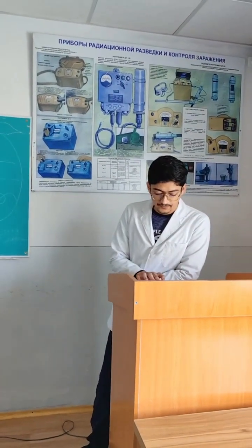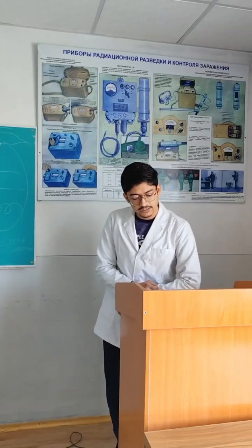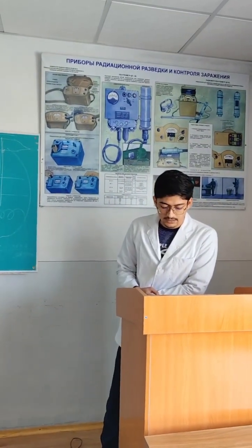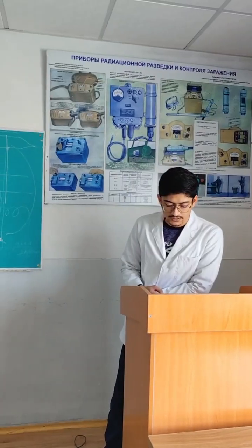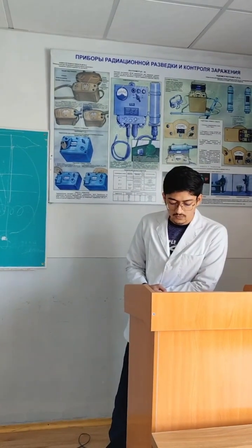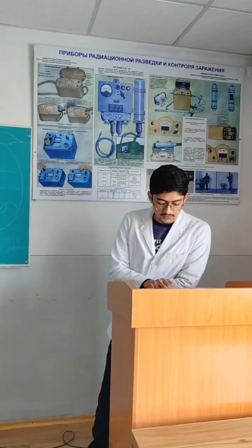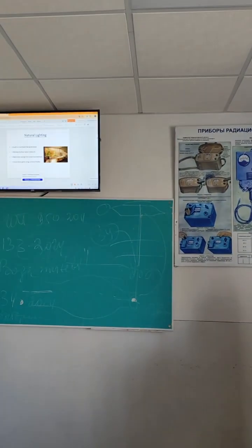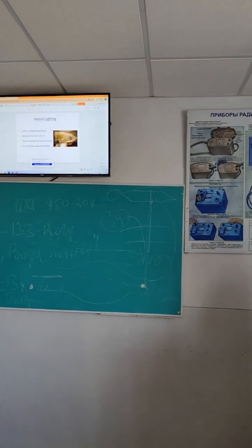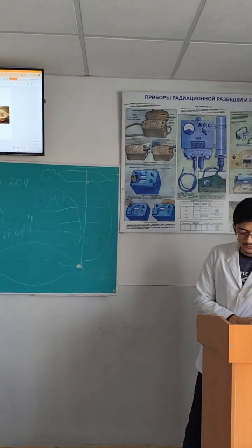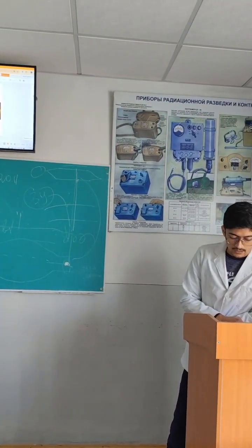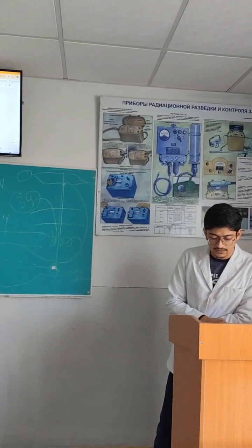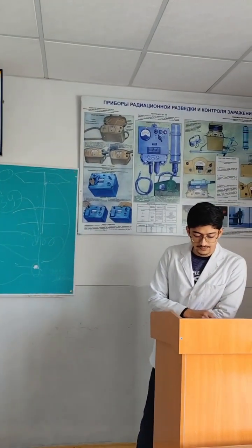Principle of placement. Building position for sunlight and cross ventilation, therapeutic block near central area, rehabilitation and recreation facing gardens, no crossing of clean and contaminated roads. Natural lighting. South and south-east facing windows, a window to floor ratio of 1:4 to 1:5. Maximizing daylight for mood improvement. Avoid direct glare using curtain shades.